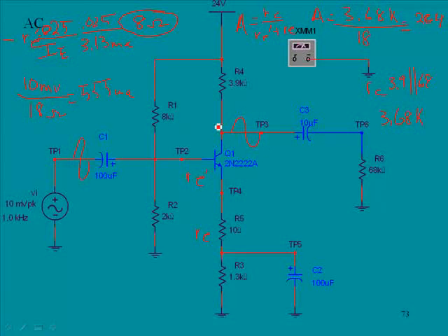Now, remember that current is going to go up here. It is an AC current, so it will be able to go both directions. And so if we took this current, this 555 microamps, times the parallel resistance here, and we said it was 3.68K, and if we take this current times this resistance, we will get 2.04 volts.